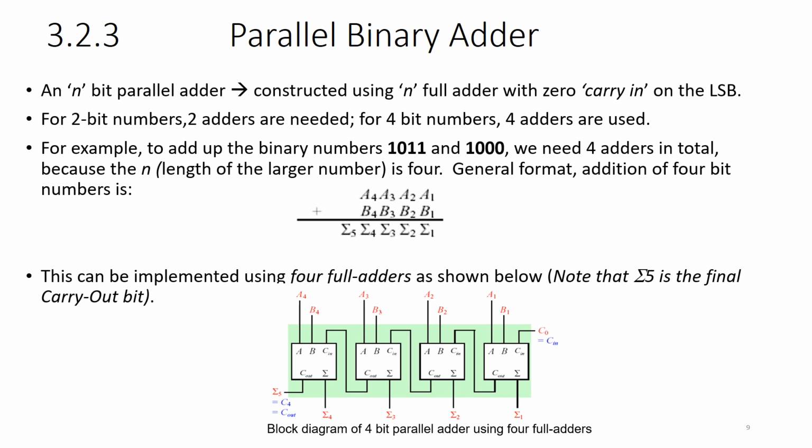So the C out of the first lowest LSB will be fed into the higher C in, and we'll get this arrangement in which we have some C out coming through. And don't forget, the C in of the first LSB should be connected to ground to give a 0 value.